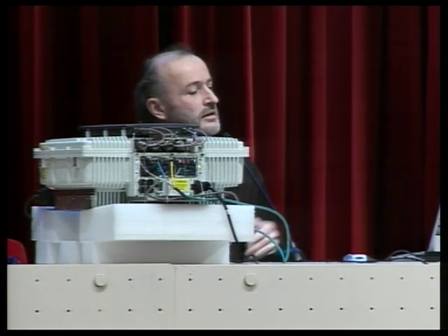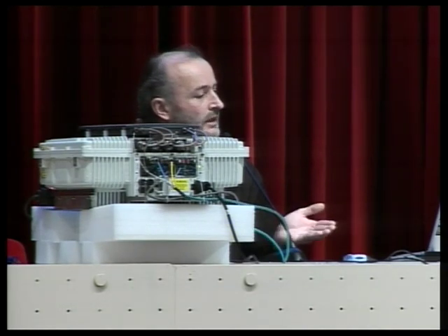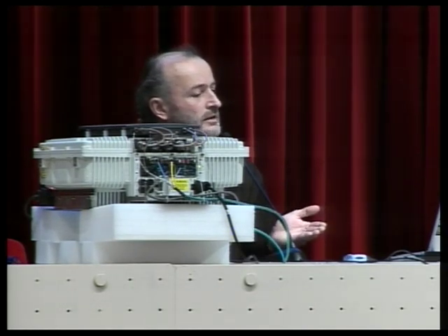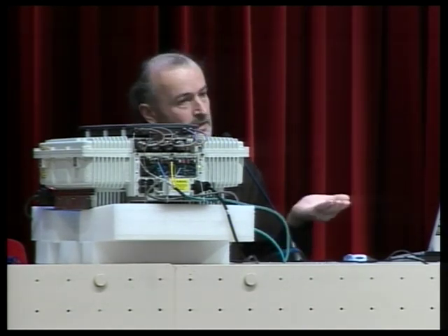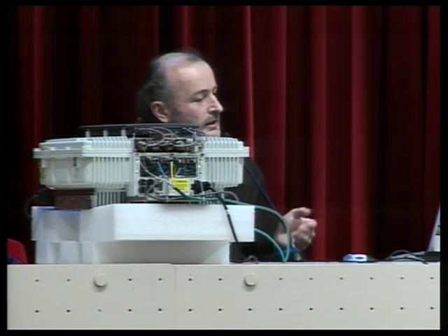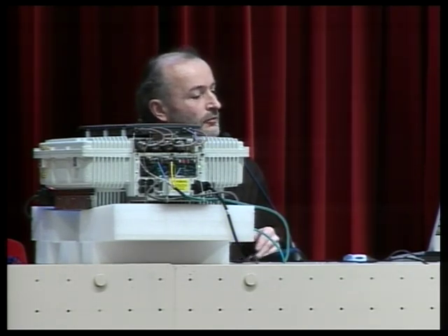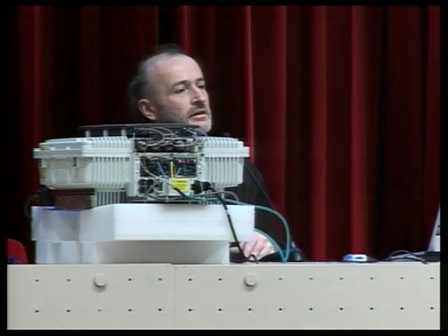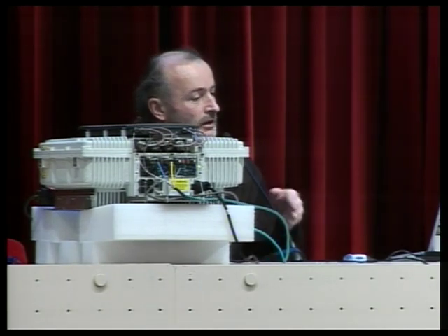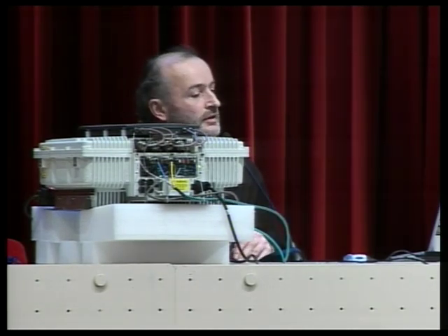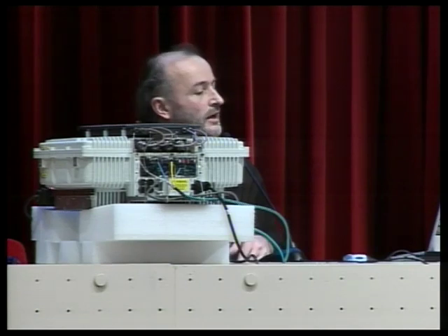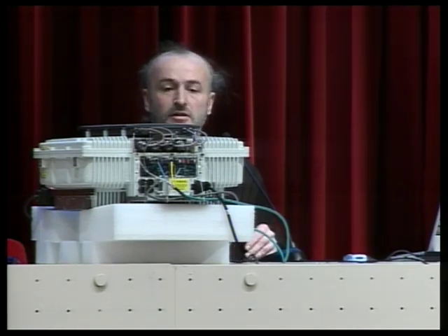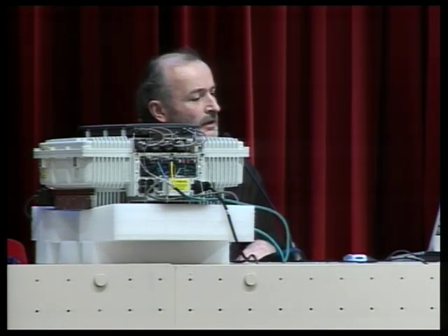The most common ones are full rate and half rate. Full rate is 16 kilobits, and half rate is, as it says, half of that, 8 kilobits. And we have also several newer and better codecs, for example the enhanced speech codec, but in our case we only talk about the full rate codec because this is what we have implemented so far and which is also supported by our base station.